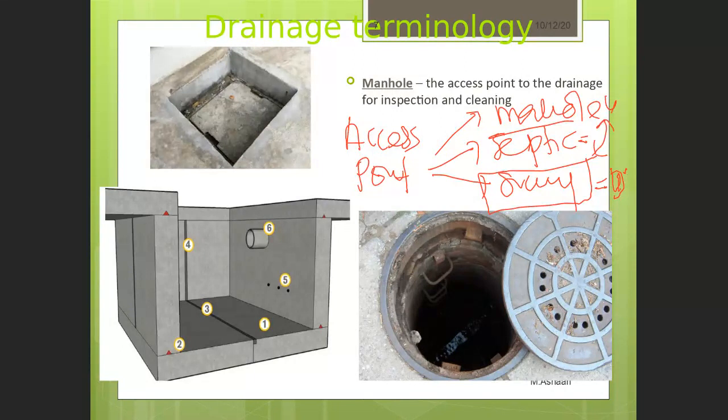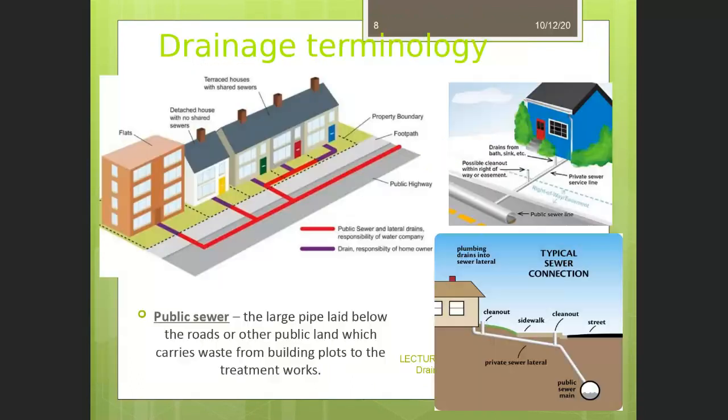Okay, the most important thing is you have to understand all these drainage systems must have their access points, normally for inspection and for cleaning. And if you look in detail, where is the access point? Access points are normally at the corner, or maybe when you have a very long run. Long run means very long or continuous drainage. You need to have at least one for cleaning purposes or to avoid any clogging.